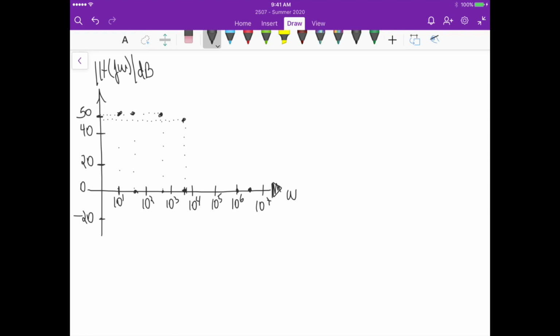So this is another point of interest that we have, right? And this basically gives us the plot. If we connect the points here, we stay at DC, then we start to decrease here, and then here we go right away down to unity gain, and this basically decreases by 20 dB per decade.